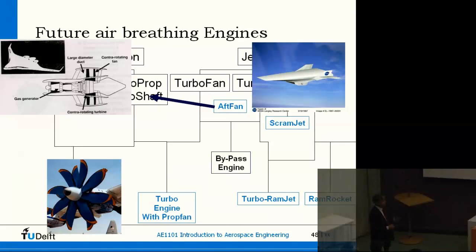Of course, recently we also saw military hypersonic vehicles. There's still research ongoing for hypersonic vehicles, and they use ramjets, but then a different type of ramjet. In all the engines that we have seen so far, the air is compressed but also reduced in speed. The speed inside the engine is subsonic, because otherwise we get shock waves and all kinds of trouble.